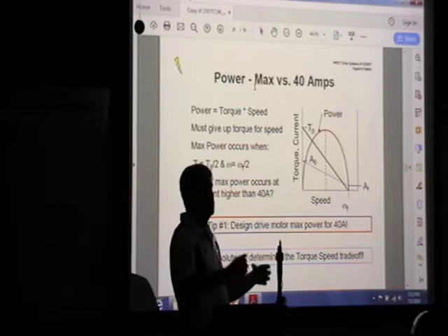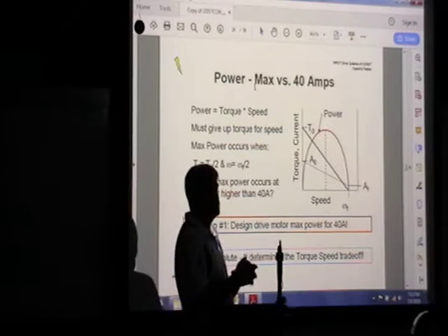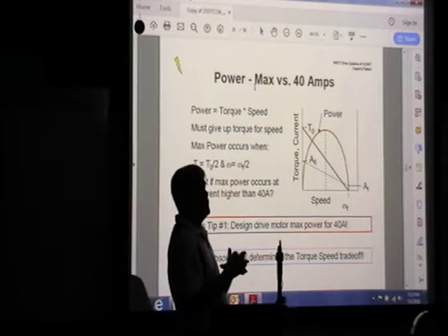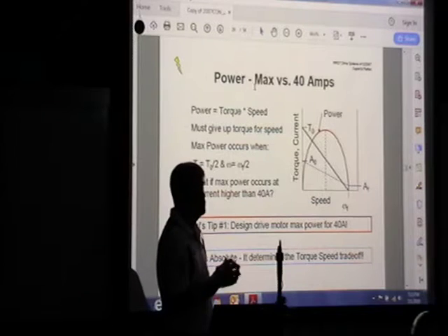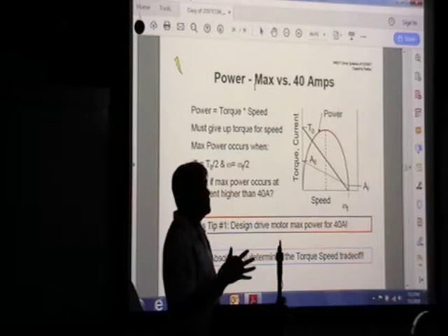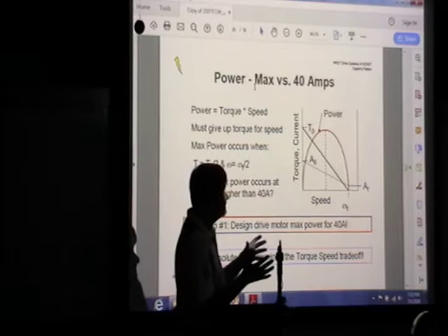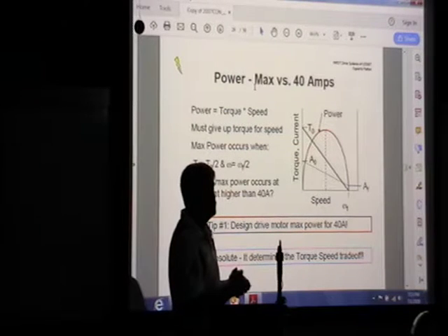Gear it, absolutely. Change the ratios so that you could get back down into that power band if you're running too fast, or if you're not running it fast enough, you gear it up so it'll run faster. A lot of those motors that FIRST supplies can do 15,000, 20,000 RPM. Use it until you get the power to it. Use those 40 amps. Gear that thing up.